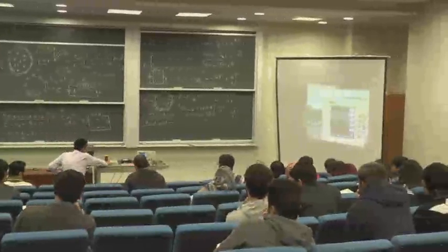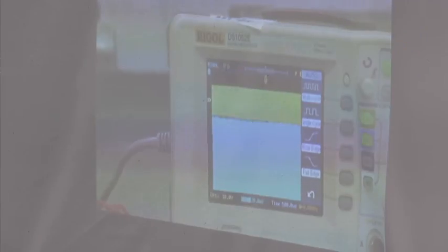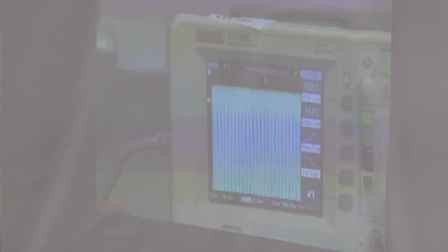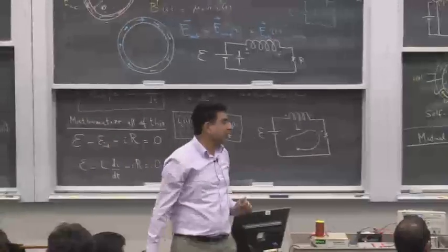I'm now increasing the frequency, it's 2 kilohertz. The frequency is going further up. So I just move these blue lines downwards. This frequency is now increasing, it's about 3 kilohertz. The induced EMF is going up, and now I'm in the range of 5 kilohertz. I've just increased this to 52 kilohertz, but now I'm outside the range of the amplifier. Alright, so the induced EMF also has a strong dependence upon the frequency.